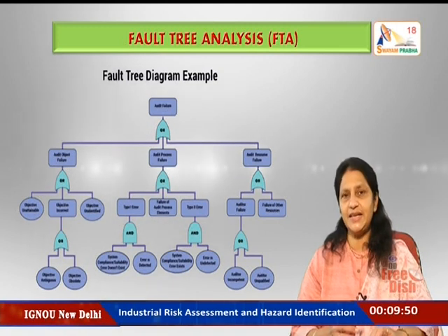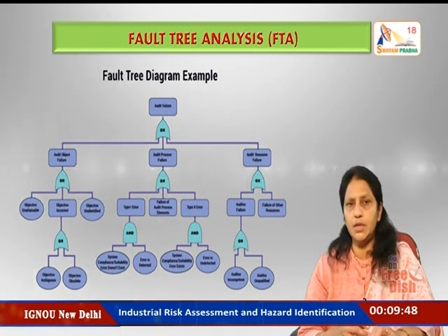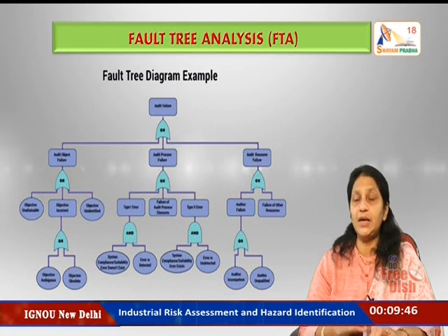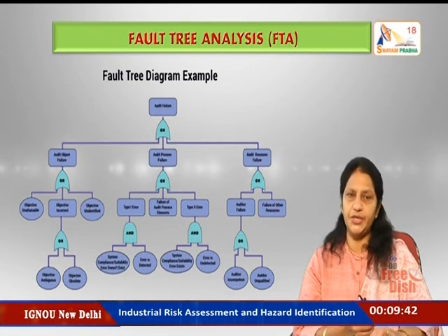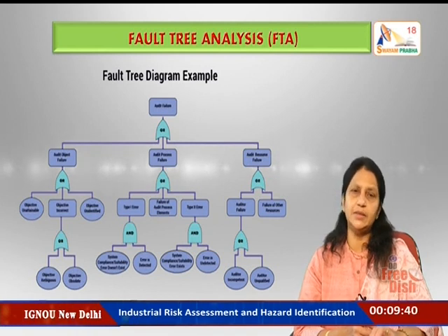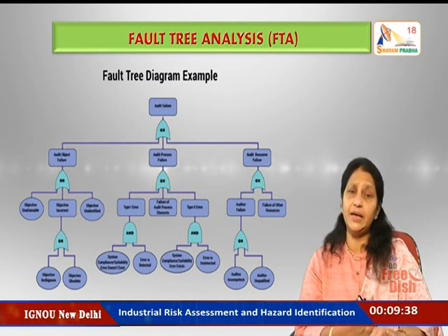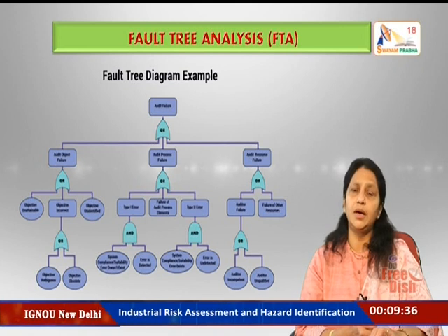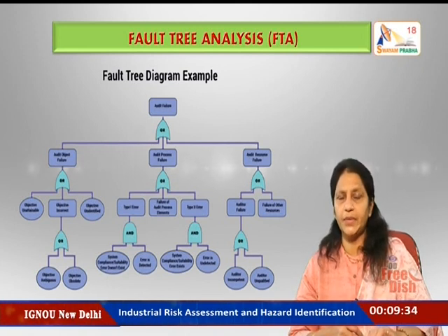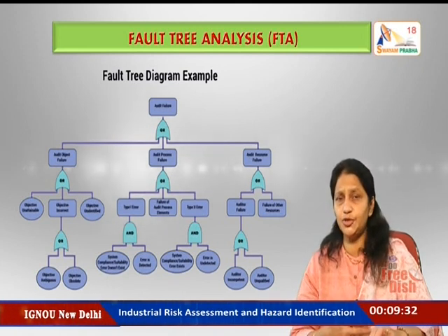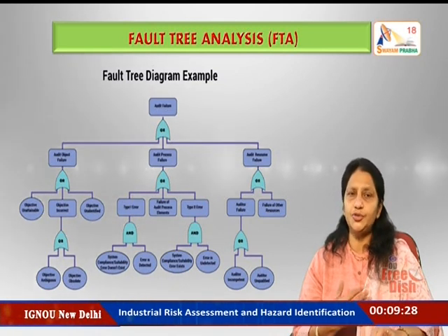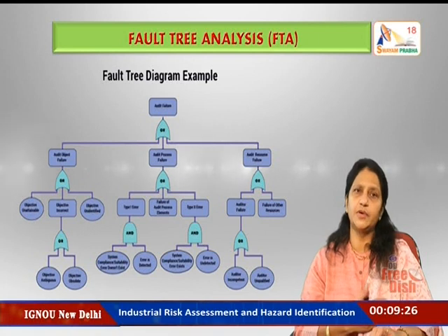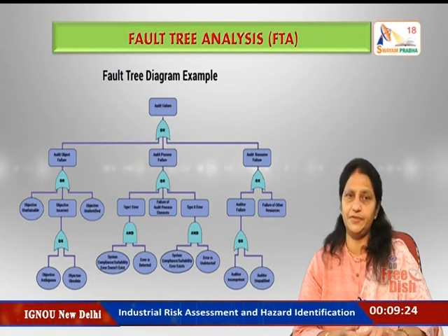The fault tree is developed from the top down, that means from the undesired top event to the primary events that initiated the failure, with logic gates indicating the passage of the fault logic up the tree. Each event should be traced back until it cannot be developed further, either due to lack of knowledge or because no other causes can be identified.